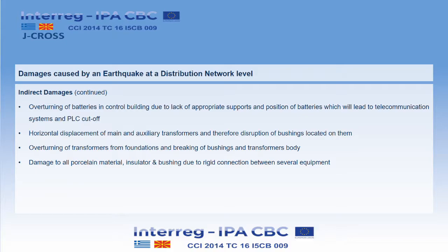lead to telecommunication systems and PLC cutoff, horizontal displacement of main and auxiliary transformers and therefore disruption of bushings located on them, overturning of transformers from foundations and breaking of bushings and transformers body, damage to all porcelain material, insulator and bushing due to rigid connection between several equipment.